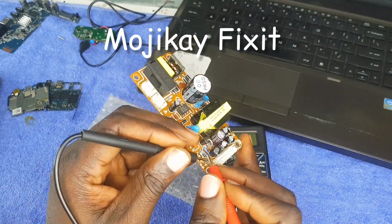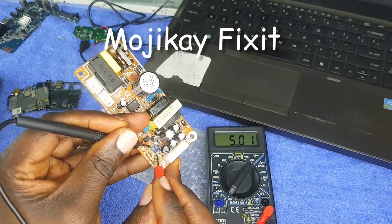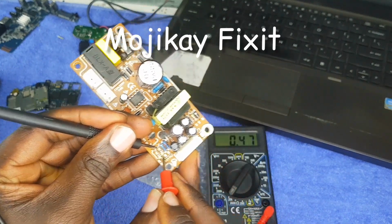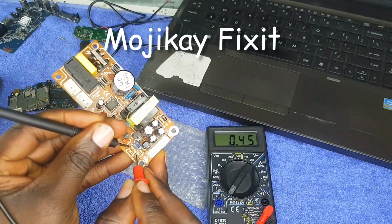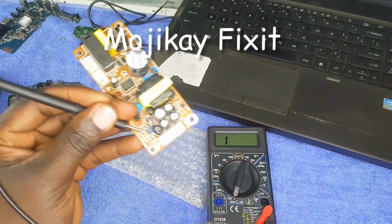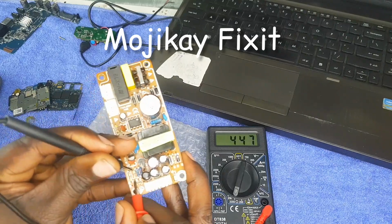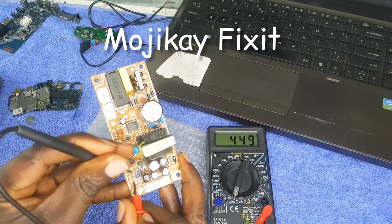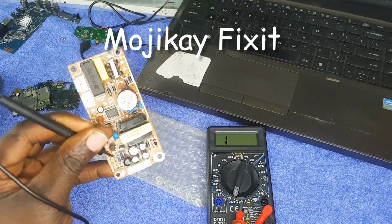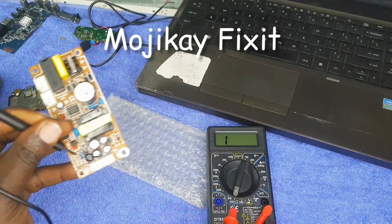So it doesn't matter how you put it. The second one, the value, that's 5K. Okay, this one is 0.4 ohms. As this one is reading 0.4 right now, we can easily put it on 2000 to get a more accurate reading. Yeah, this thing is painful. As you can see, that's 449 ohms. So if you put it on this 200, it will not read properly. It will not give you an accurate reading because 200 is less than 449. So that's how to read.